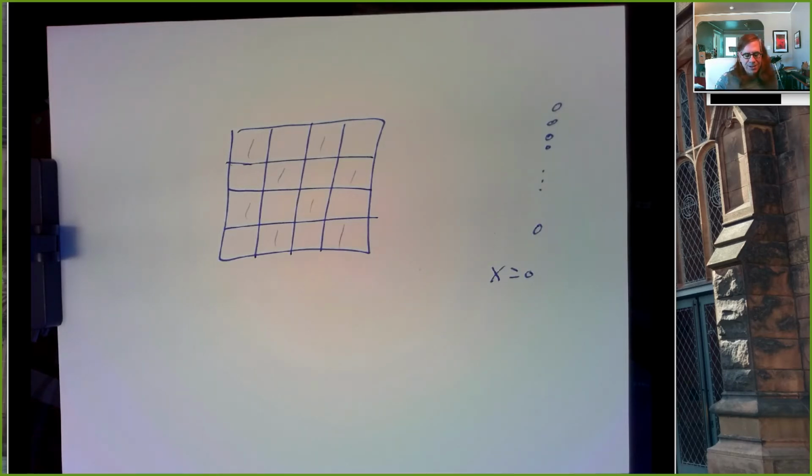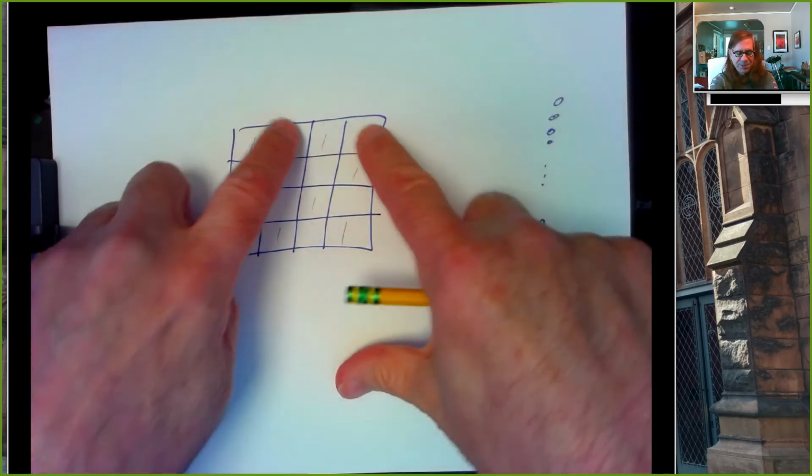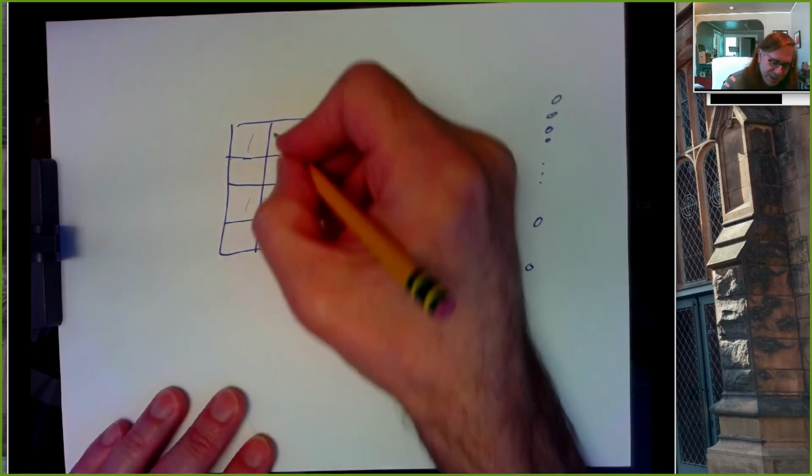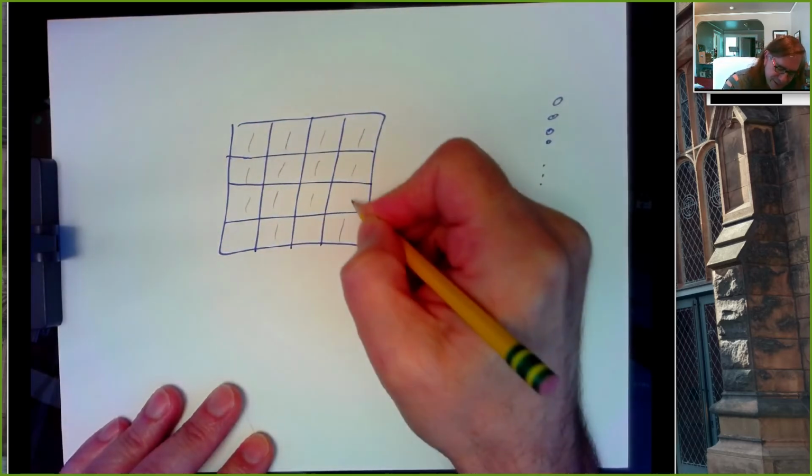What's the other? Just do a mirror image, so put the ones in all the spots that are open instead of the ones that I drew it in. It's the same situation. Well, that doesn't even simplify at all. Oh, well, I wouldn't consider it the worst. That means you don't have to do it. Well, that's true. Worst in terms of what you have to do next, which is build the thing. But yeah, very, very little work to do the K-map part. And so these correspond to exclusive OR and exclusive NOR functions, which we have other chips for, so we can do things with that.